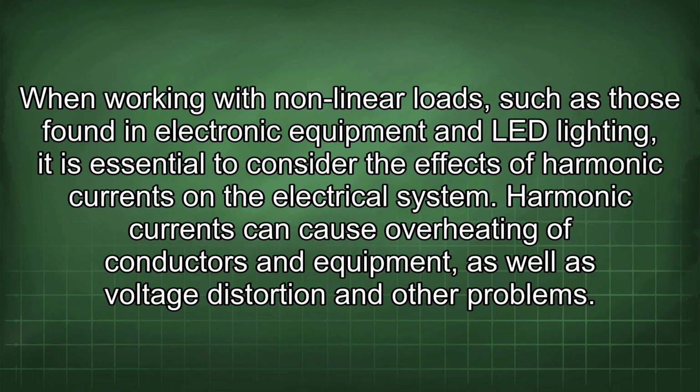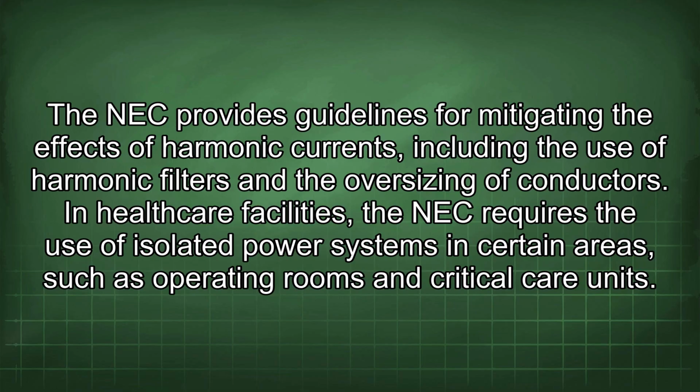conditions. When working with nonlinear loads, such as those found in electronic equipment and LED lighting, it is essential to consider the effects of harmonic currents in the electrical system. Harmonic currents can cause overheating of conductors and equipment, as well as voltage distortion and other problems. The NEC provides guidelines for mitigating the effects of harmonic currents, including the use of harmonic filters and the oversizing